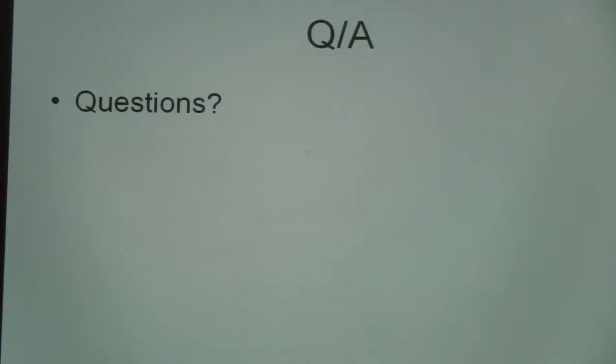The AVR data sheet makes mention of a multi-machine UART configuration with addressing. I've read a lot of the data sheet on the UART stuff, but it's not been something I've ever actually had to do, so I haven't looked at how that works. I don't know if that's something you could make work with the Pi as well, or if it's some specific app model. Now, if you wanted to talk to it from a Due or a Raspberry Pi 3 or 4, that would work because it has multiple UARTs.